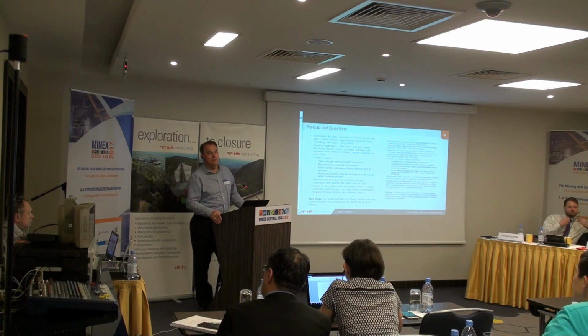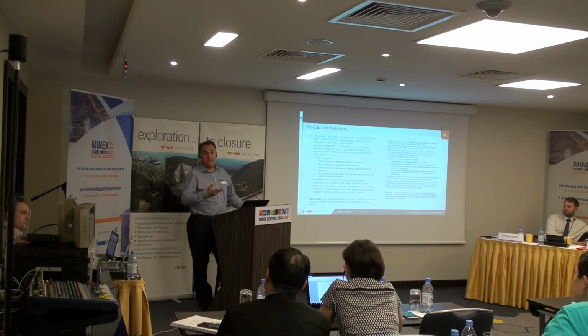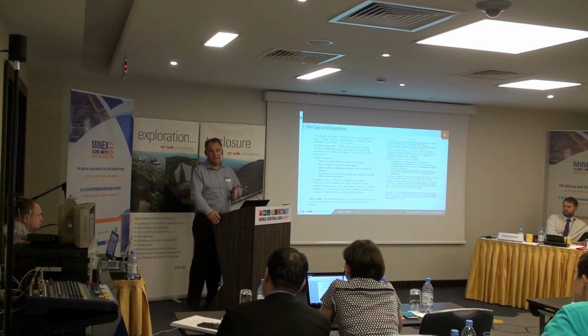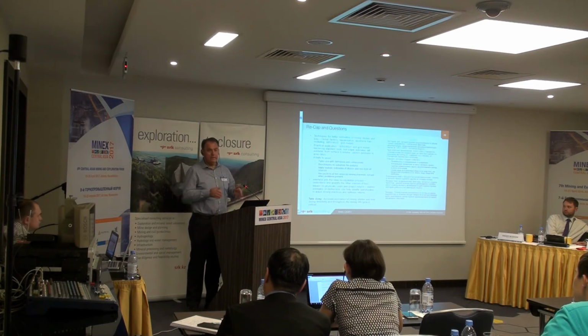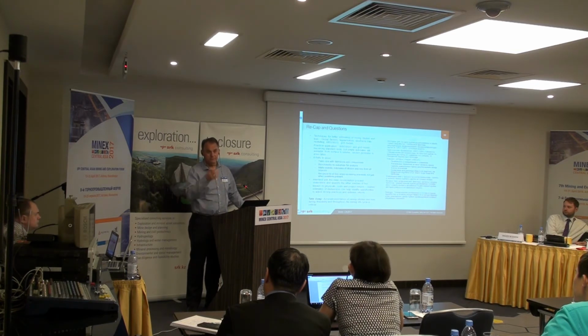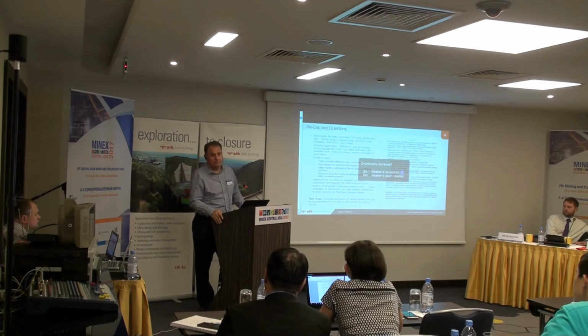Yeah. Okay, from a practical perspective, during the 80s, certainly in Australia, in my experience, with an open pit, you would implement what we called blast vector indicators. And essentially what that is, extra drill holes throughout a shot with a white plastic pipe inserted, no explosive, just inserted in the shot. That would be blasted, say, on a 5-metre bench.